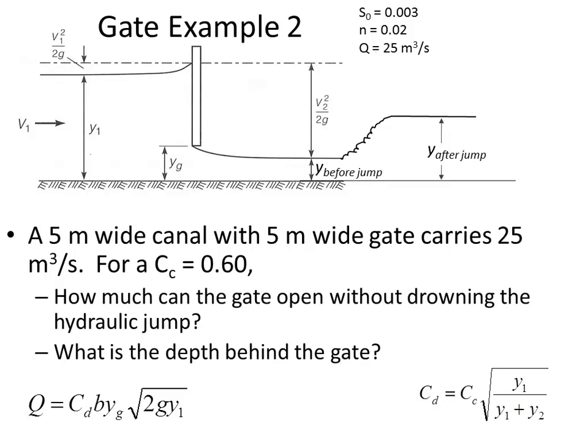Okay, so we use the solver for the normal depth, y sub n. The normal depth is in a couple of places in the equation, so it's not easy to separate it out and solve that algebraically. We can either just put it into the calculator with the equation solving function, and if you've not figured that out yet, remember that there's the video tutorial that Dr. Pearson put together online.